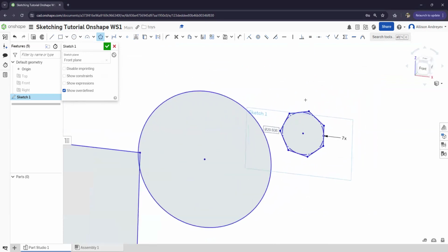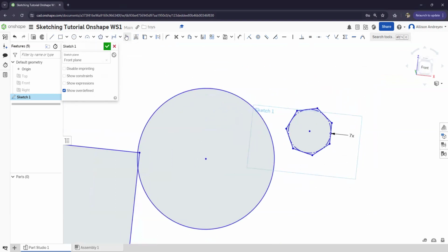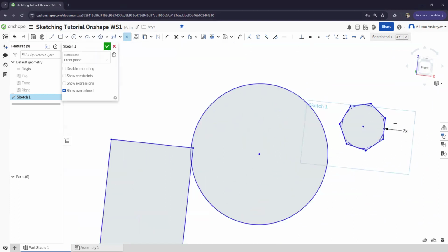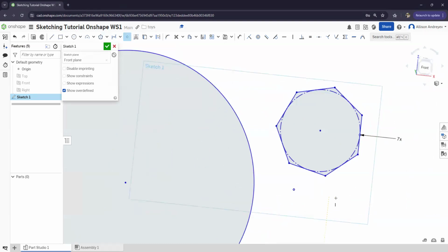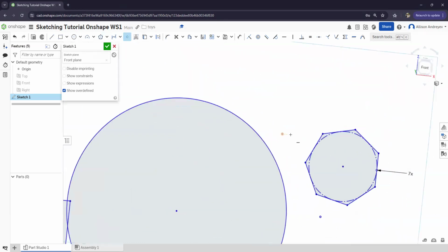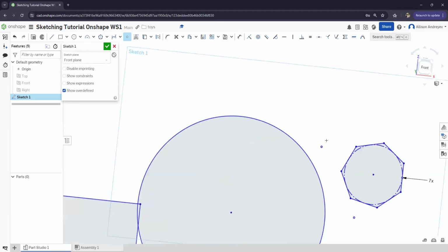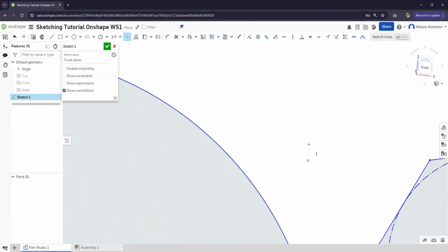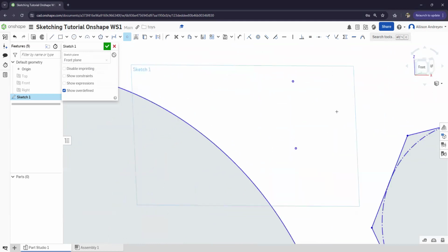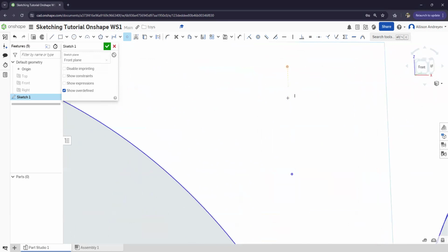Another thing you can do is draw a point in sketching. This can be a simple plot, or the point can be strategic. Let's say I want to draw a point that is parallel at this point. If I hover over here and move my cursor up, it gives me a straight line and shows me my path. It lets me know that this point is now exactly above this line.